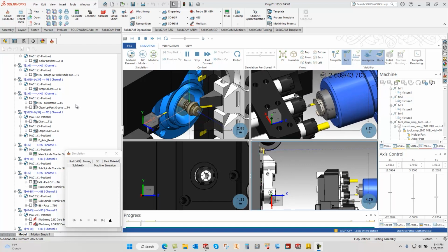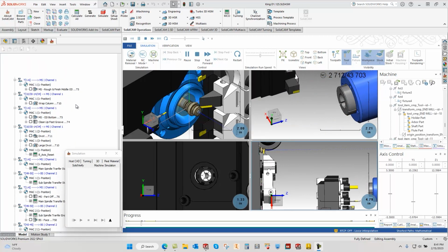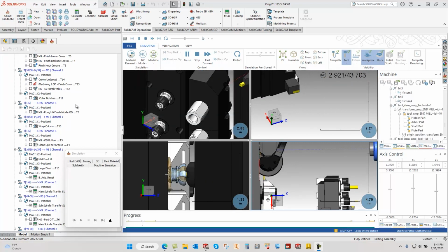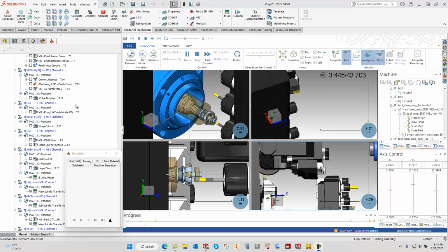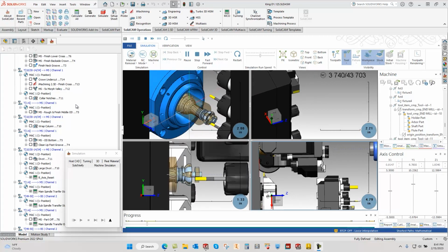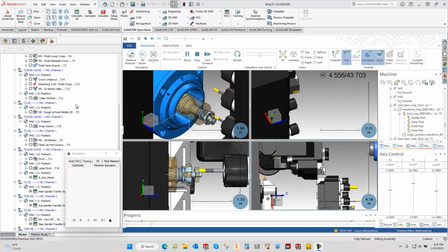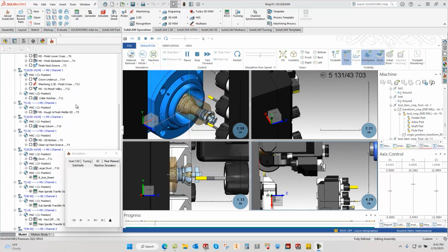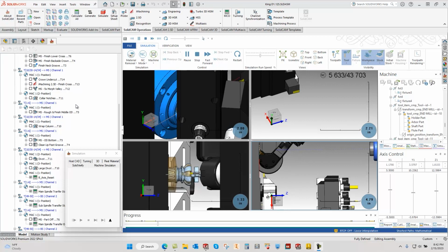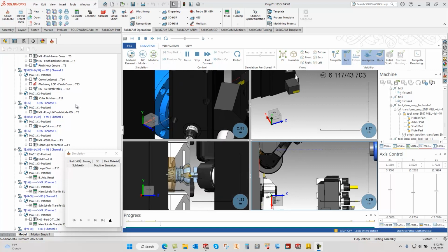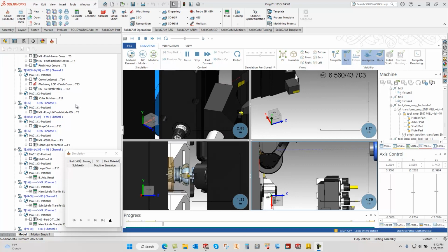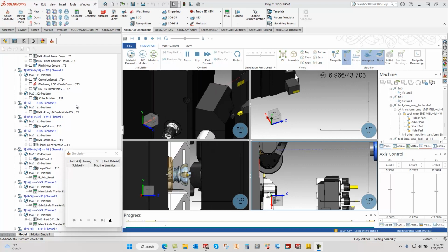You're going to need a really good post processor. Some of you might have some post processors that you were guaranteed were out of the box or certified, yet they're still not working, or maybe you haven't gotten yours at all. Maybe that'll work fine for 3-axis Haas, but when it comes to these more complex and increasingly more complex CNC machines, you're going to need a good post support and post people behind you. Now, this particular post was built by Eric Forwith, one of our many in-house post-processor writers. But you can also edit these posts or create them yourselves.